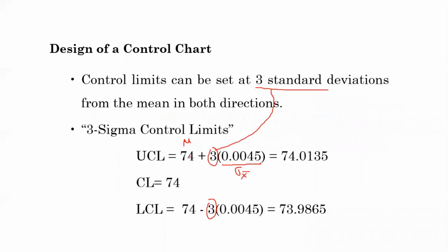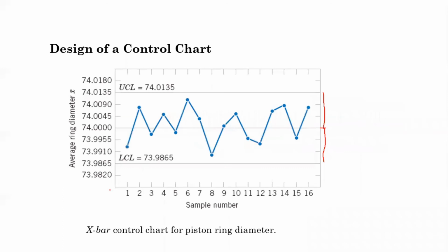Then, using these, you can compute the three elements: the center line, the upper control limit and the lower control limit, and you could use the sample averages to plot these values easily. Later, when we come to each classification, we will explain further. Now normally, as I said previously, what we are looking for is a point beyond the upper or the lower control limit.